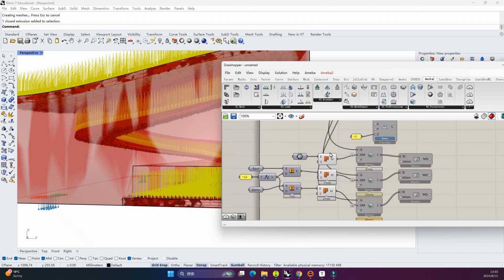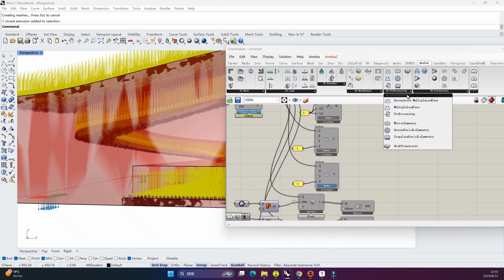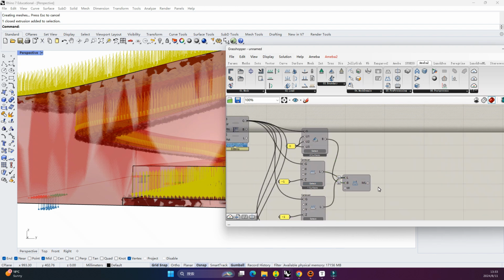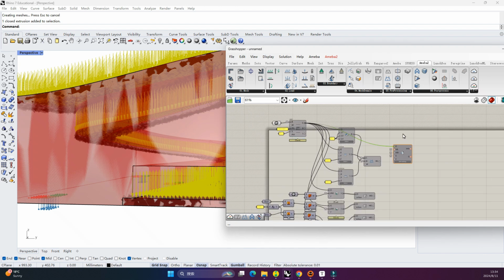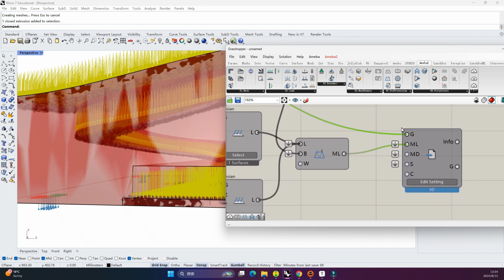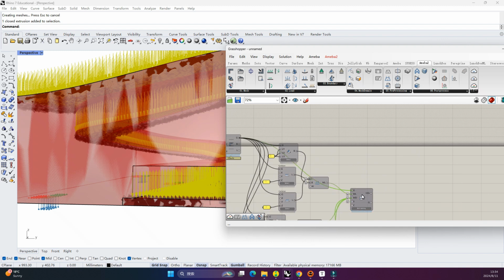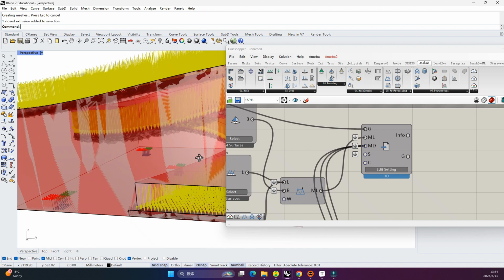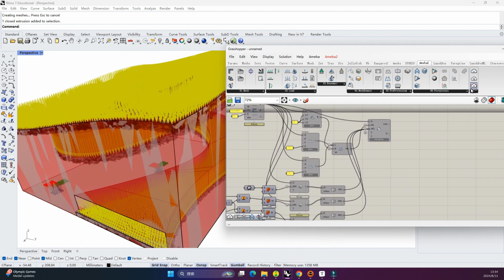So the next step, we can collect all of these conditions together. We can use multiple load keys and connect with the support, and then we can use pre-processing. Use G here and connect the multiple load keys and non-design domain. Okay, in this way we have already defined the loading and boundary condition and the non-design domains. We can start to do topology optimization.